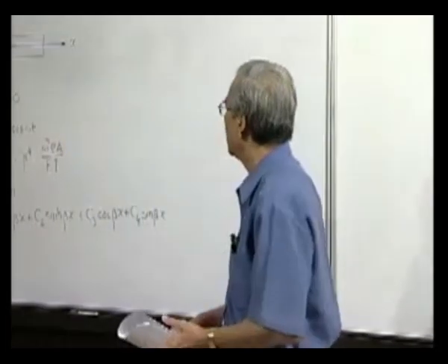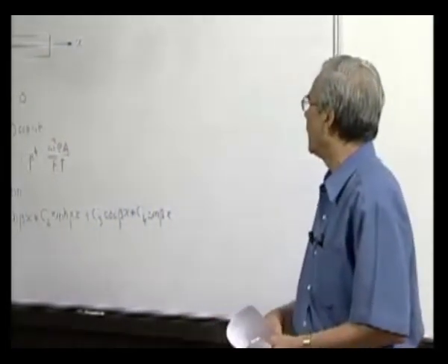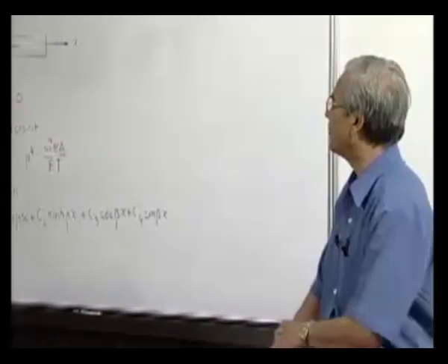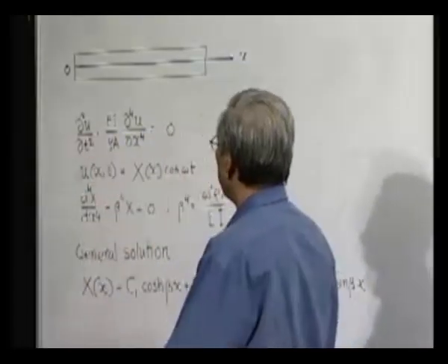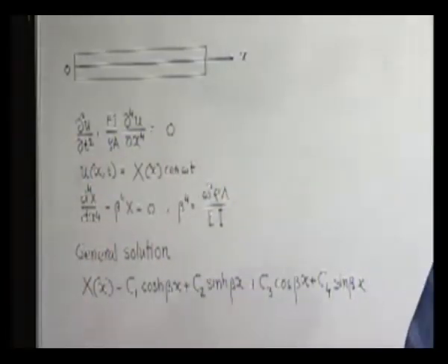So, we have solved the problem of transverse oscillation of uniform beam. We derived the equation of motion valid for a general element, which is this, where U represents the lateral displacement, which is a function of both its location, that means x, and also the instant of time under consideration.